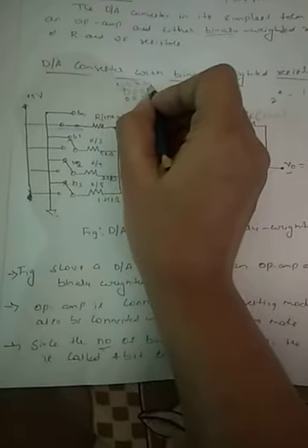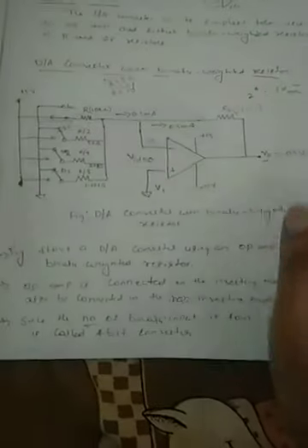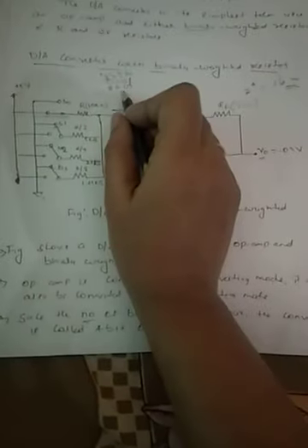So next, in the next case, when the switch B1 is closed, that is when the input is 0010, this is for 1, this is for 2. This is 8421, therefore totally 16 combinations. So when switch B1 is closed, the switch B1 is connected to plus 5 volts and the remaining switches are all grounded.